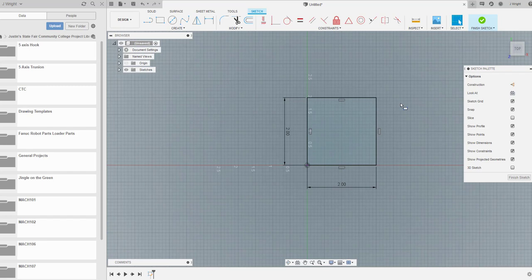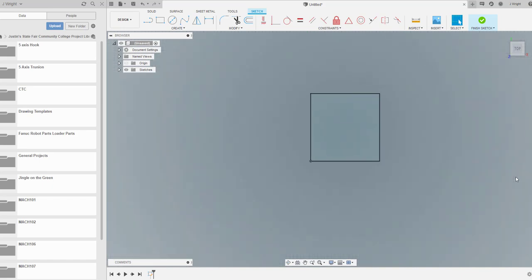All the sides, the four sides around the part, we're going to drop this into a fixture, into a vise, into something. And all we're going to do is face mill the top side, run that racetrack down inside of there, drill and tap that hole all the way through. So we've got our stock. From this point on, I'm just going to hit finish sketch.